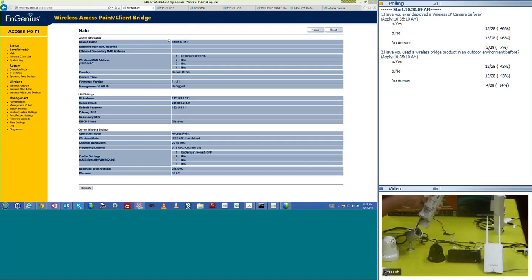On the back here, by the way, it's got a nice little link quality thing here. And I'm actually connected right to each other, and the link quality is good. Now, I hope the link quality is good because they're 2 feet from each other. But you'll also notice that on the back here, it's kind of shaped like a pole. And the reason why it's shaped like a pole is because we typically will take these and mount them to a pole interface and then use zip ties, preferably the zip ties that will not erode with direct sunlight, and we'll zip them to a pole, and then we can zip these two and aim them at each other.